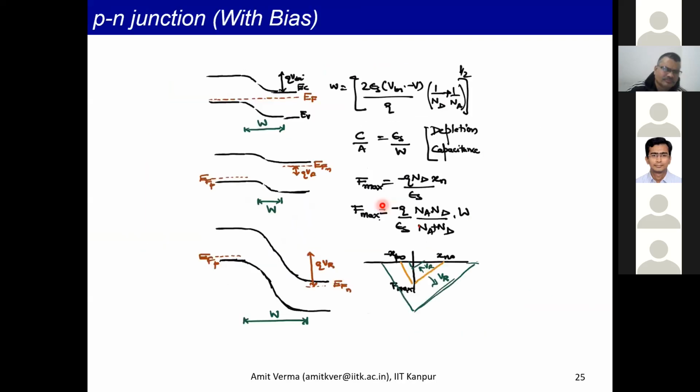Even for polycrystalline samples, we can represent the band diagrams, no? Yes, you can. For polycrystalline silicon solar cells and all, we regularly use band diagrams. Some things do change: depending on the grain size, the band gap can change also. Suppose your grain size is very small, then the band gap can increase. Those kinds of effects you will have to take into account. But as long as the grain sizes are much larger than the de Broglie wavelength, let's say more than 100 nanometer, you can keep on using the bulk band structure and make the band diagrams accordingly. Okay, sir. Thank you.